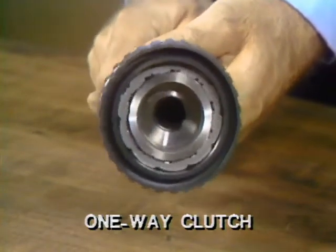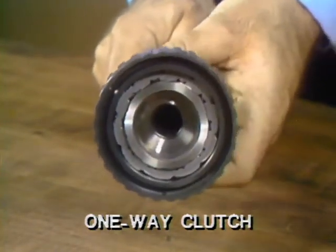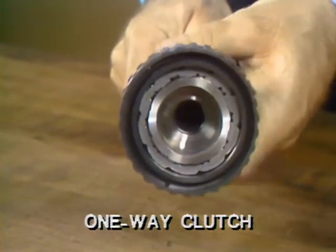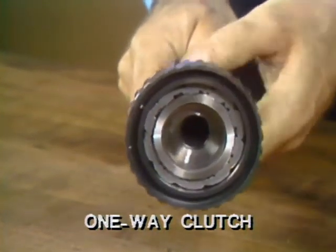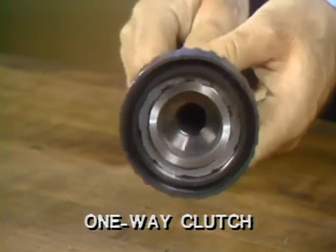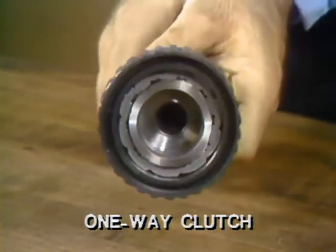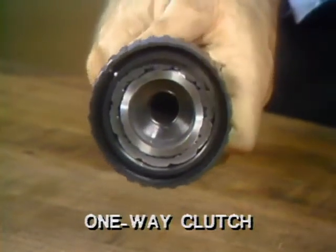If the sun gear overruns the turbine shaft, the clutch freewheels. As we'll see presently, this is how we get a freewheeling low gear. This then is a unique feature of the ATX, a one-way clutch with both races rotating instead of one race mounted stationary.